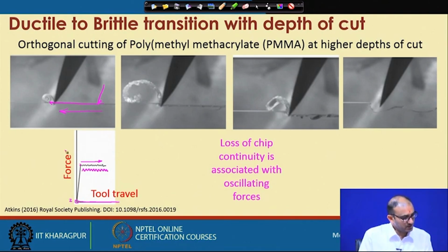This variation is small because the depth of cut is very small, and the amount of material being removed from the workpiece is also very small. So, let us consider this a reference signal, a small signal. We are not getting any disengagement between the workpiece and the tool, because the tool is in full contact with the workpiece throughout the cut.